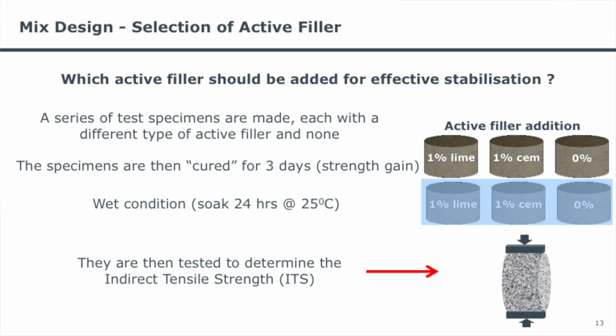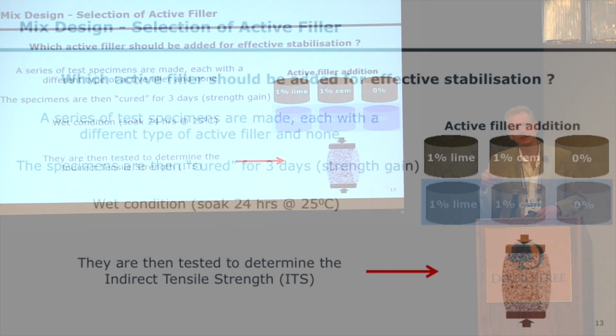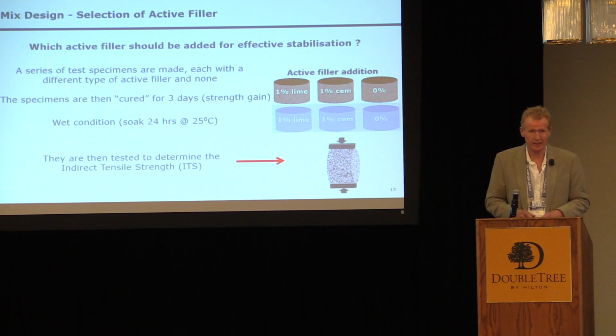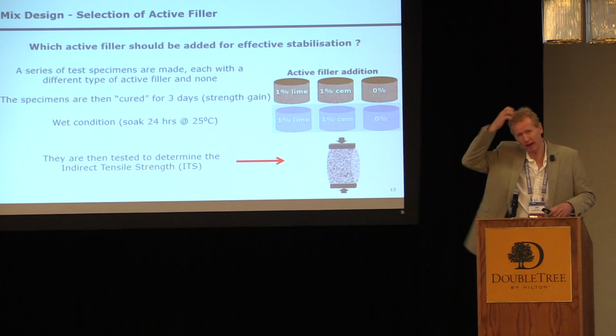and then one will obviously cure those specimens and test them all at 25 degrees. Although it's stabilization, some people still need to get their head around the fact that temperature is an important consideration, an important variable when one's doing this testing. And we test at 25.